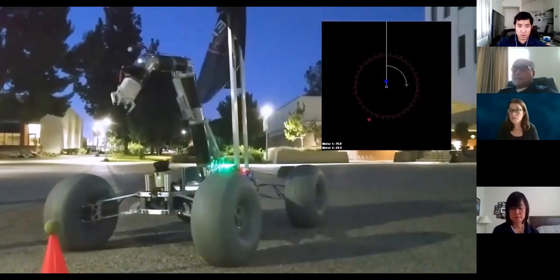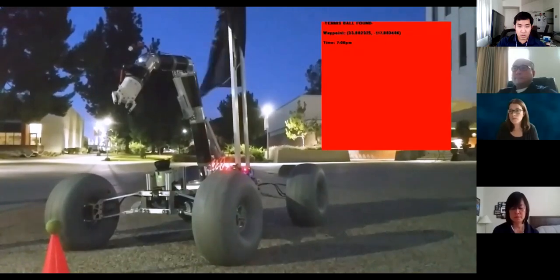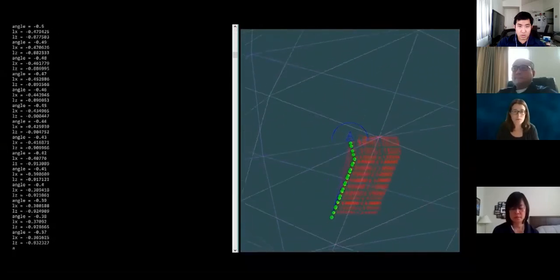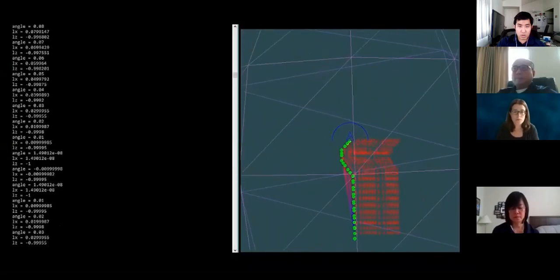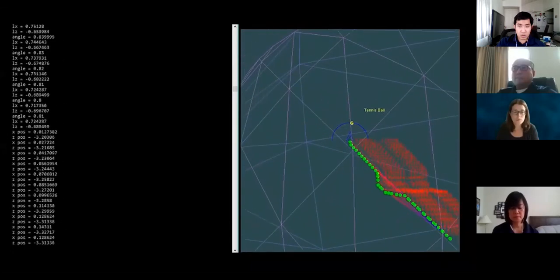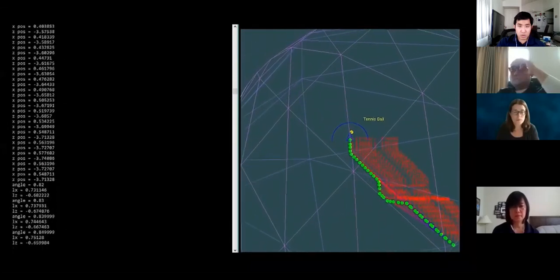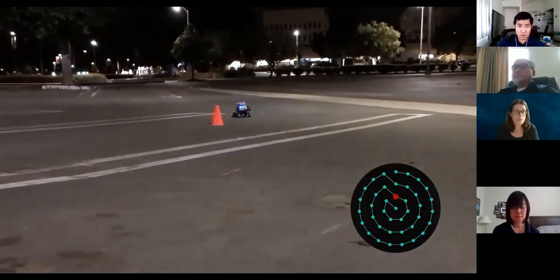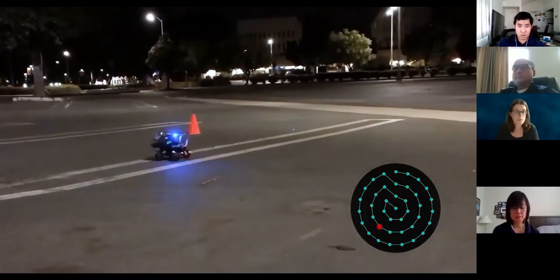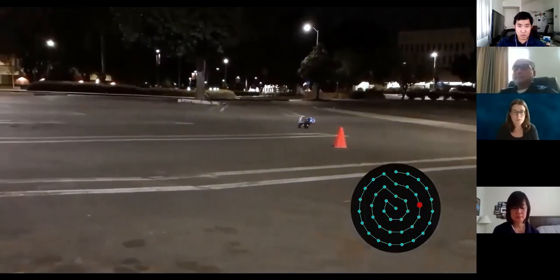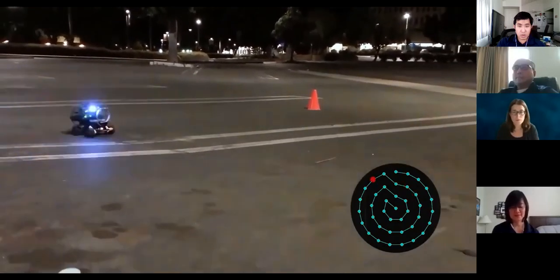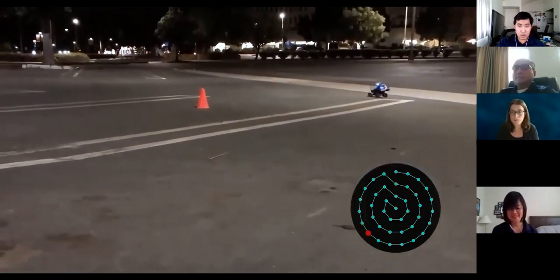Our navigation platform is based on a simultaneous localization and mapping model within the Robotic Operating System. Our sensors will construct an environment in which the rover will operate. After reaching the provided GPS point, a mathematical algorithm will create a search pattern based off of known system and vision constraints. This will include any prior obstacles that the rover has encountered and added to the SLAM model.